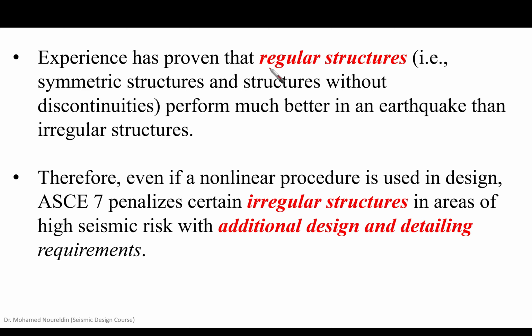Experience has proven that regular structures, meaning symmetric structures and structures without discontinuities, perform much better in an earthquake than irregular structures. This is actually going to be taken into consideration in ASCE. Therefore, even if a nonlinear procedure is used in design, ASCE 7 penalizes certain irregular structures. And this is an important issue that you're going to find.